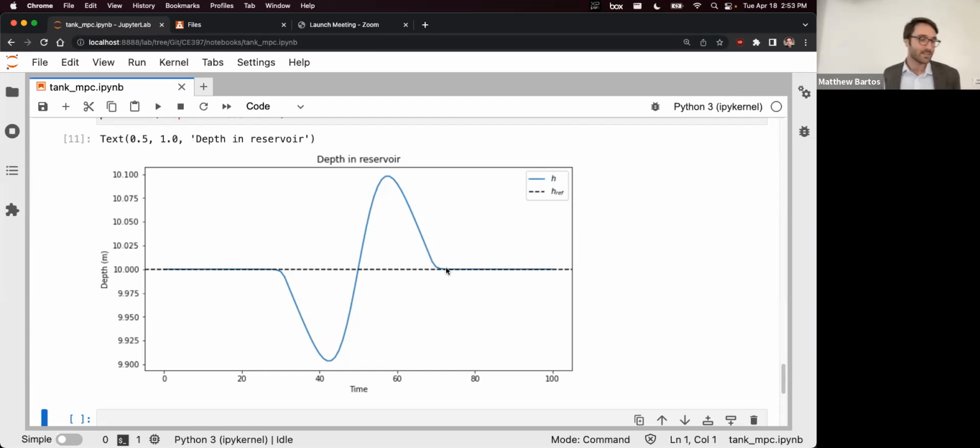So I should note that in model-predictive control, what we've done is we've essentially solved the MPC problem for one time horizon. Typically in MPC, you'll have a streaming control problem in which you take one time horizon, you solve the optimization problem for that time horizon, you implement just the first control action or the first couple control actions, and then you move the window forward to a new prediction horizon and solve again. So this would be implementing just one of those time horizons. Typically, you just keep moving the window forward.